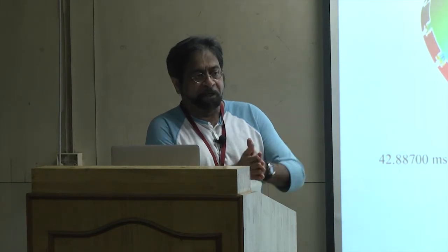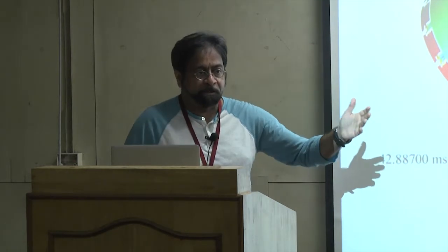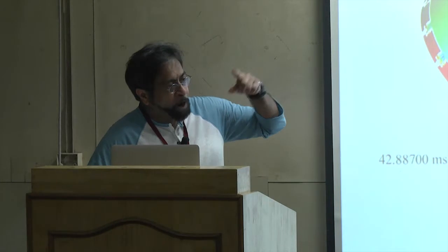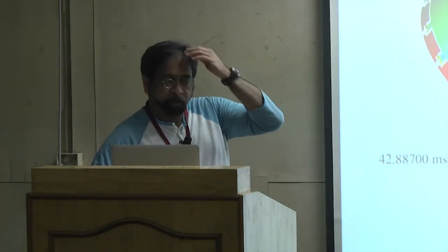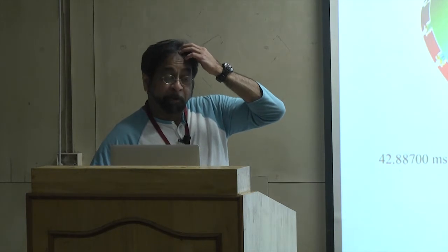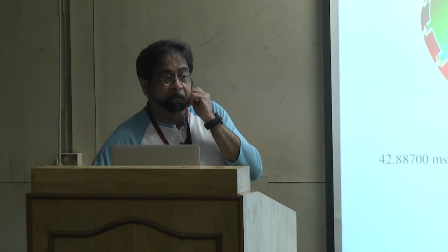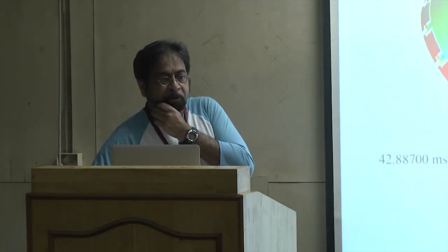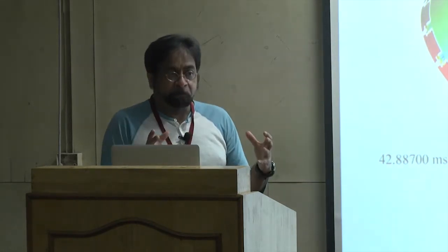Well, the flame transfer functions are dynamic. In other words, you're basically getting some number of transfer function after you're post-processing it, right? Yeah. And then the question is when you incorporate coupling to the flame transfer function, the acoustic analysis, the coupling should be in the same mode as in the real system. That's usually where I think they have a problem. And then I'm not very familiar with all the latest flame transfer functions, how they do, but like the impedance boundary conditions, yeah.